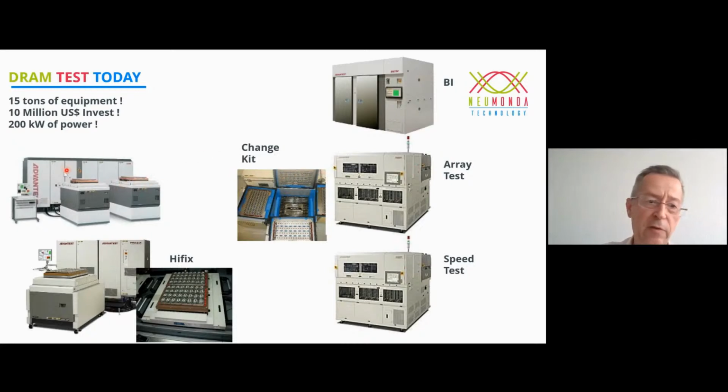For this, you need a tester, typically with 2 test heads, and then a related handler. The handler is moved above the test head, and the handler then moves the components there and away. This array testing you typically do twice. At high temperature, then you move the memory components out, and later you run it at low temperature.